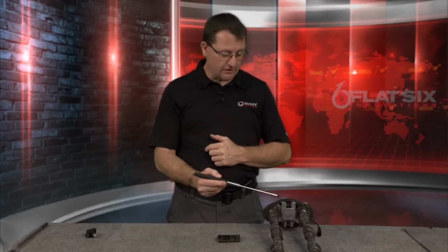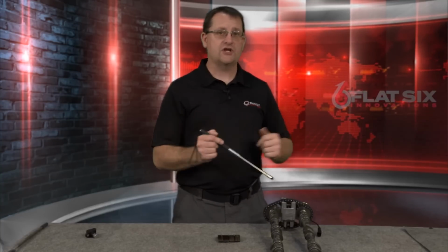So what are some of the things that lead to that? One is mechanical. It's never perfect. Some of these chain adjuster units move more than others do. Okay? Sometimes one side of the engine has higher oil pressure than the other side. Is that supposed to be that way? No, but we found that there are some things inside the engine where some of the oil galleries sometimes, especially in the cylinder heads, will not get as much oil flow up into the chain adjuster.